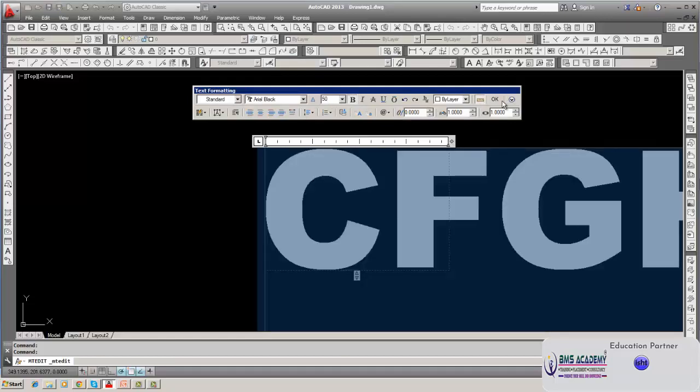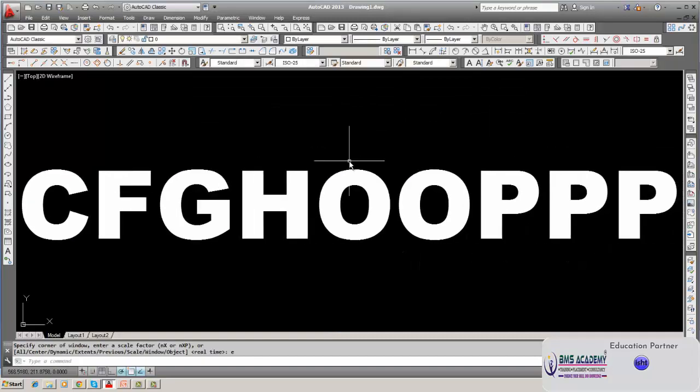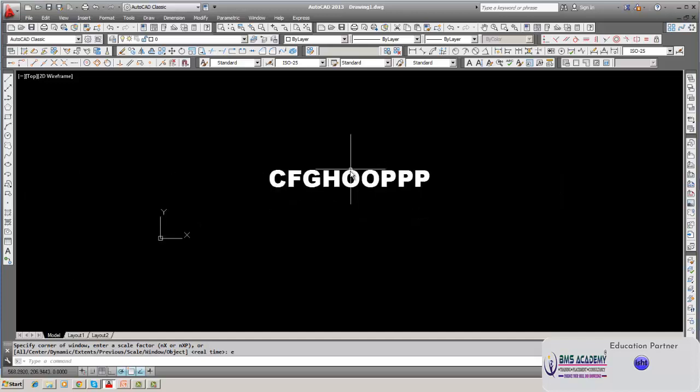So this is so big a letter. If you print this on the paper, the drawing will be reduced to 1/10, that's 200 mm and 100 mm, and this letter 50 mm is reduced to 5 mm. So this is also reduced, no? That means the letter should be multiplied by the reciprocal of the scale factor.